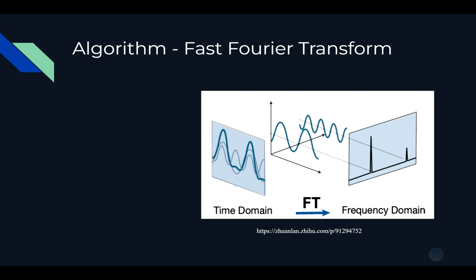You can see that it converts the audio from the time domain to the frequency domain based on different frequencies, because different frequencies can reveal more details about the signal. In the frequency domain, we have a real part and an imaginary part. For these two parts, we apply the filters so that we can eliminate the useless information, and then we can do the inverse fast Fourier transform.